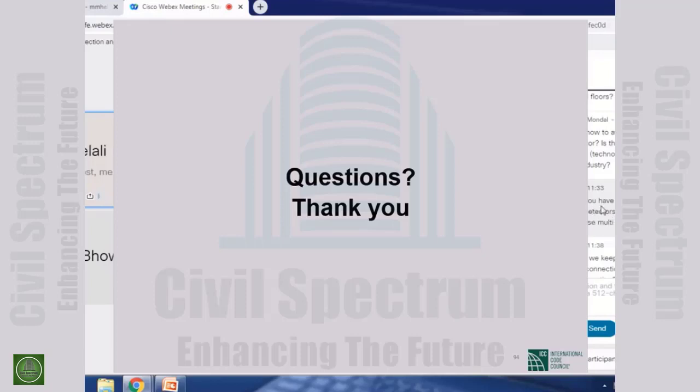The next question: as you have said to use a single type of detector, what should we consider to use multi-detector? You should consider the detection efficiency. You should consider the false alarm. You should consider the air flowing tendency of our nature, because in our nature, we always keep our windows open. We will keep our exhaust system open. This is our nature. In Europe, in America, they don't keep it open.